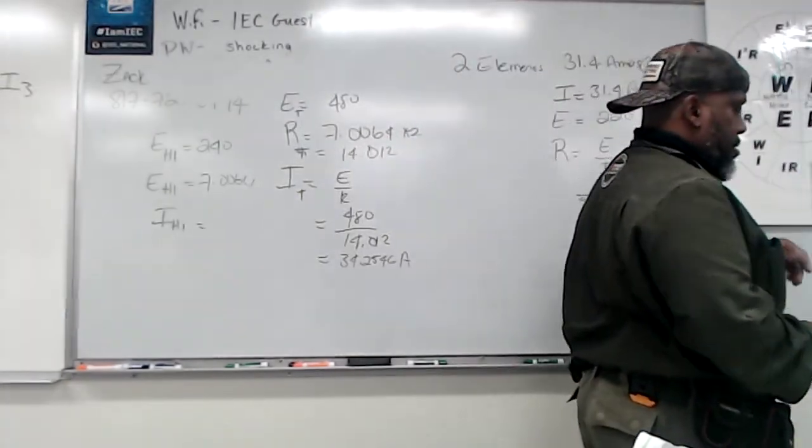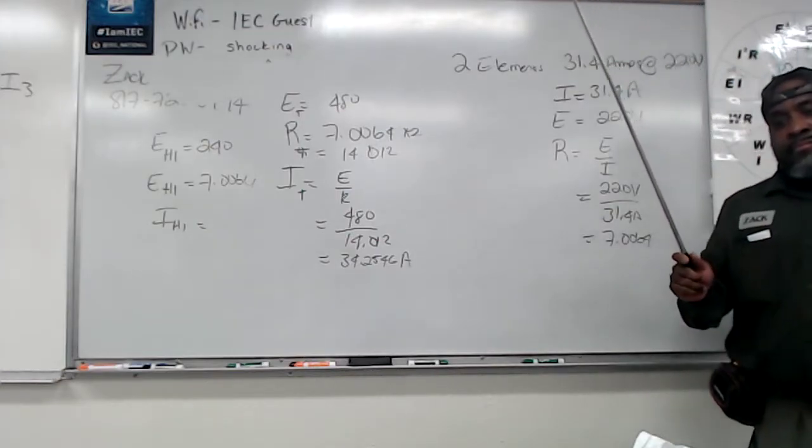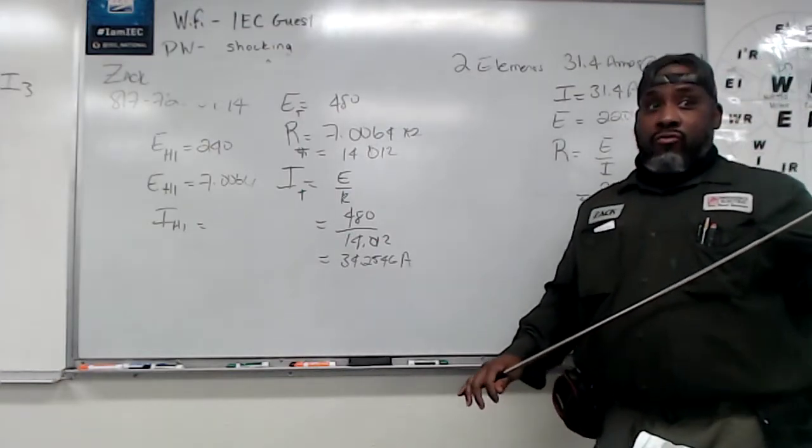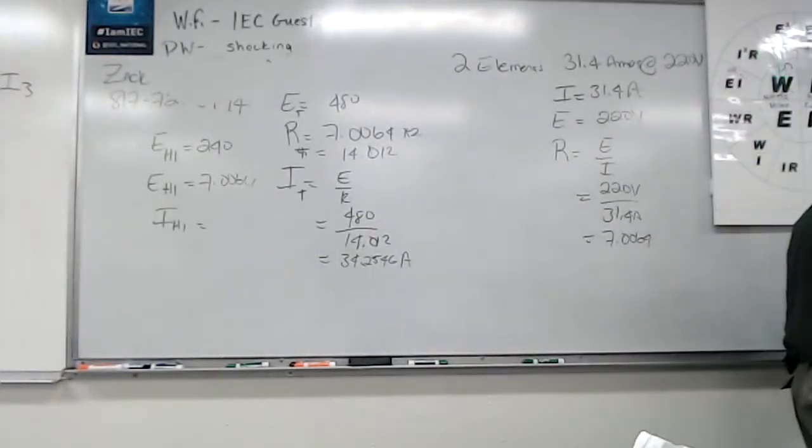Check this out. The black wire is connected to the left half. The red wire is connected to the right half. Same thing here. Got that? It took me a minute, on the screw. Y'all didn't know this, but that little tab between those receptacles could actually be broken off. You can break it in half, and you can have two separate circuits on one receptacle. Did y'all know that?